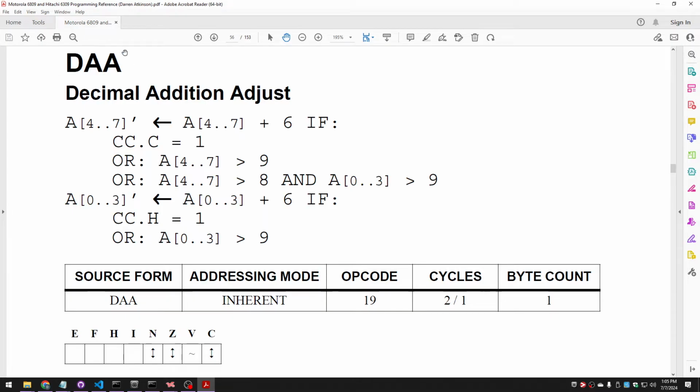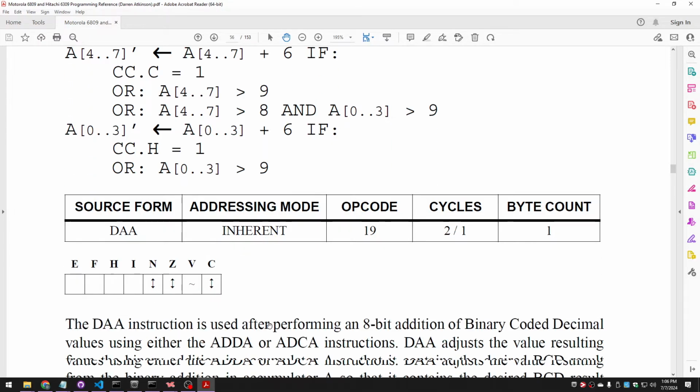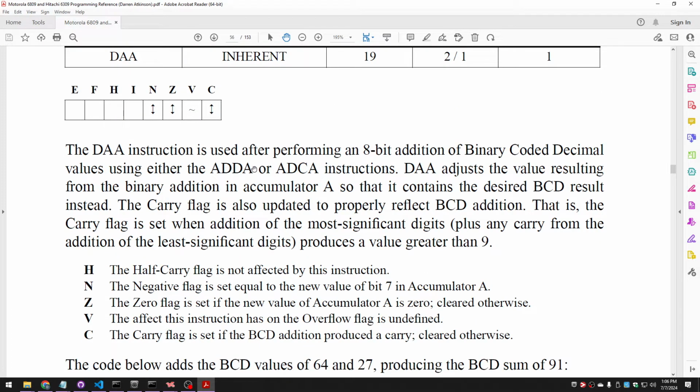It's got one and only one instruction, and this is one of the most restrictive instructions there is. Exactly one addressing mode, exactly one register that it affects. And here's how you use it. You ensure that your A register is already a binary coded decimal, and then you add to that another byte that you ensure is already a binary coded decimal. You can do the add either with or without carry. And then you run the DAA, which decimal adjusts after addition the A register.